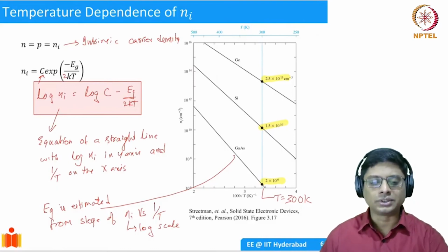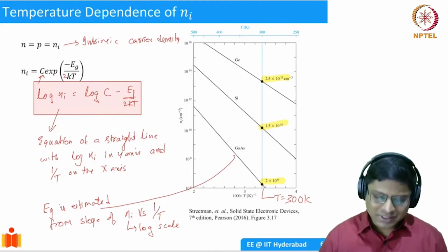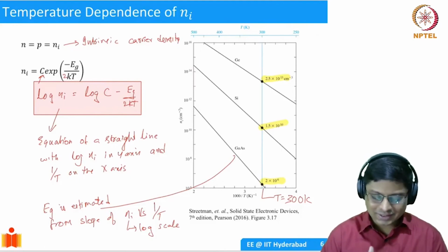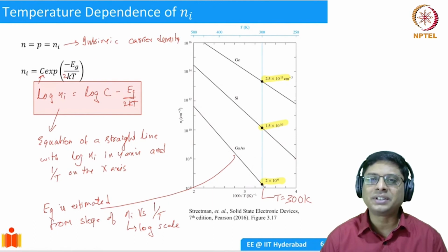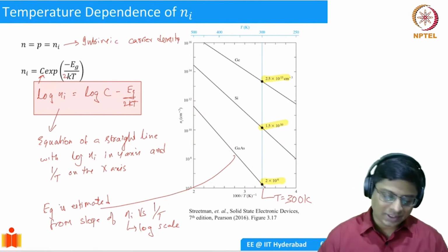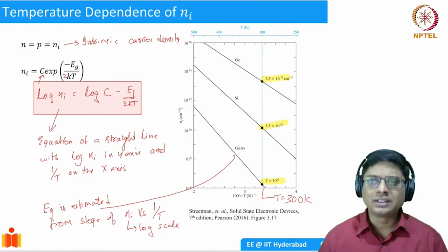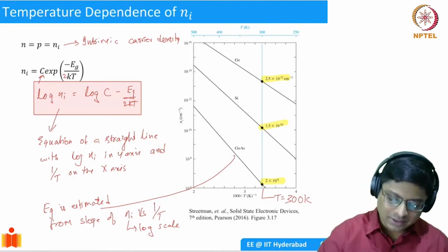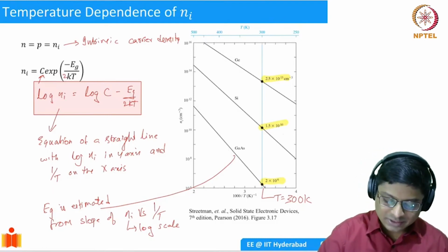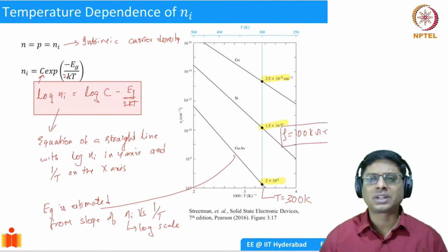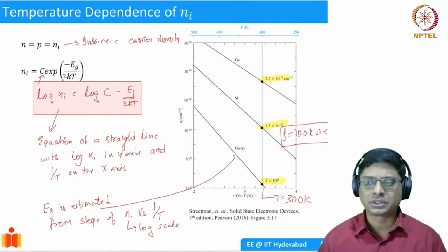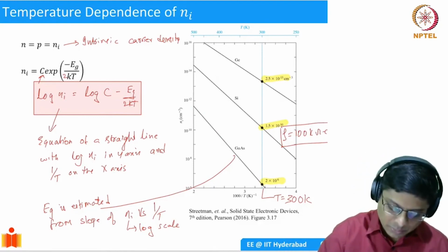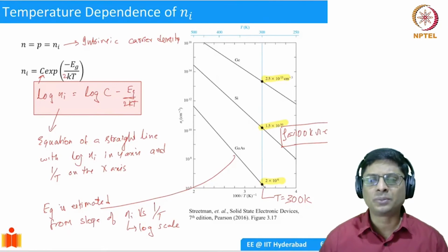All right, so good. Now, if you think about it, what is the resistivity or conductivity of silicon here? If you take silicon, this number, 10 power 10, if you calculate, the resistivity turns out to be 100 kilo ohm centimeter. This is a typical number; we will tell you how to calculate it later on, when we will give you a formula. But it's not equal; it should be approximate. Hundreds of kilo ohm centimeter.